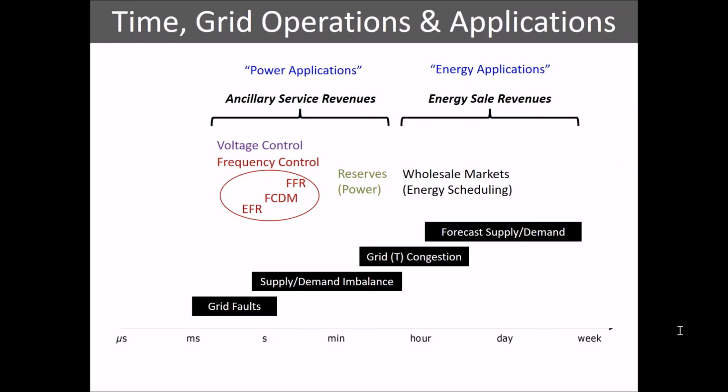It's things like faults in the grid, a power line gets struck by lightning. It's about unplanned losses of supply. A power plant, a turbine breaks and it goes offline and suddenly you lose a few hundred megawatts of supply. And those kinds of very short-term imbalances create challenges, particularly system-wide around frequency. So in Europe, at least, our grid runs at 50 hertz. If you're in the States, it'll be 60 hertz.